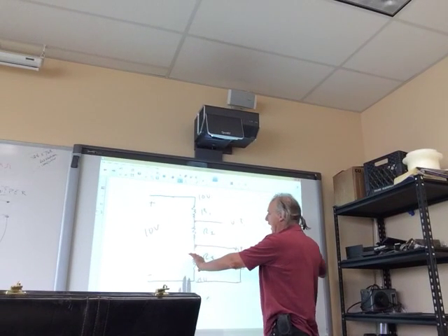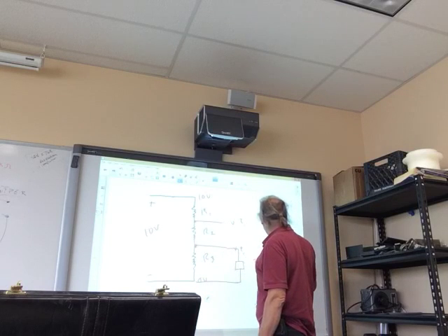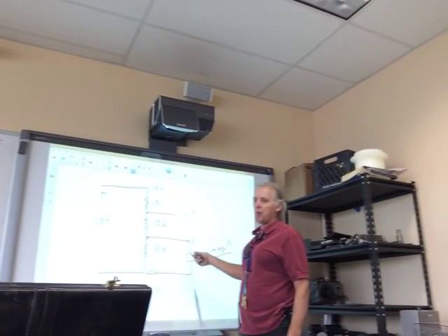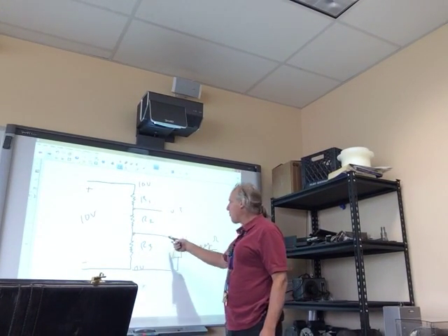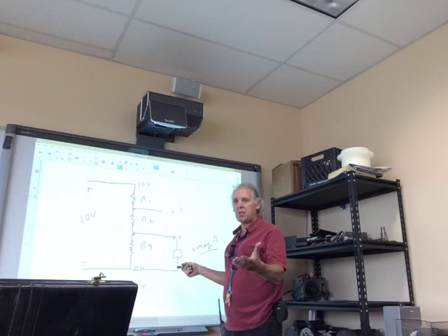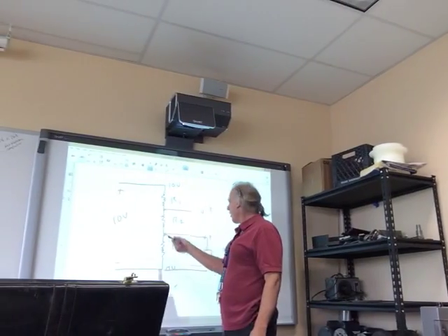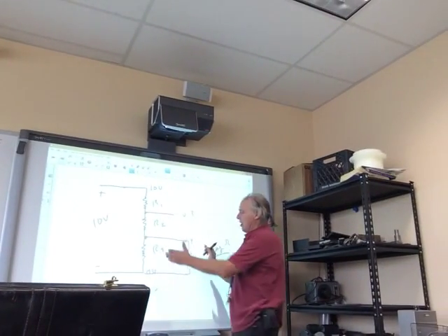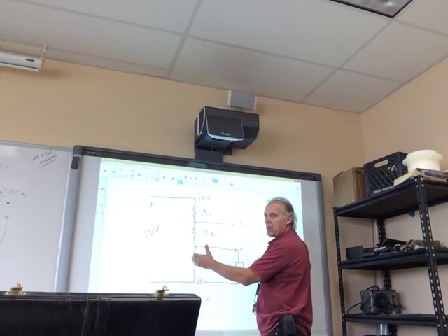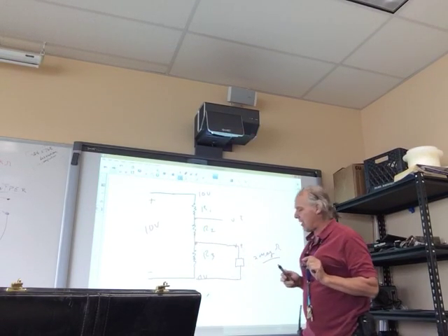Now, if this is way bigger in resistance, let's say it's like 2 megohm, it's so much bigger than this resistor, we're not going to really care. So it's a voltage-driven device. You guys talked about voltage and current-driven devices, right? Okay. So this is a voltage-driven device. So this voltage here will drive this black box here. It's in parallel, but it's so much bigger than this resistor here that it's not a big deal. So this voltage will stay proper for this voltage-driven device, the black box.